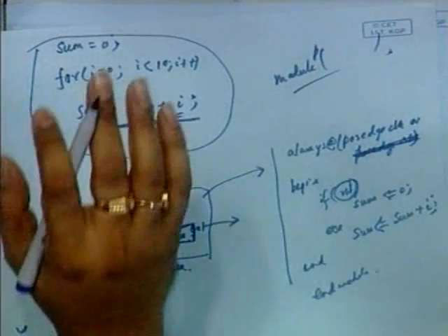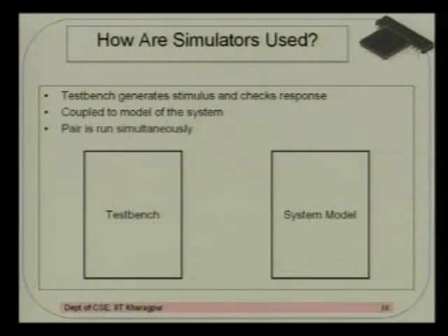So that is what I mean by synthesizable. You have to use proper synthesizable mechanisms to describe your system model, and then, in order to test your design, you have to write what I call a test bench. It's actually non-trivial to write a good test bench, because 70% of the design industry works on writing test benches only. Design effort and design money go into writing test benches, which are used to give stimulus to your design, obtain responses, and finally check your result.